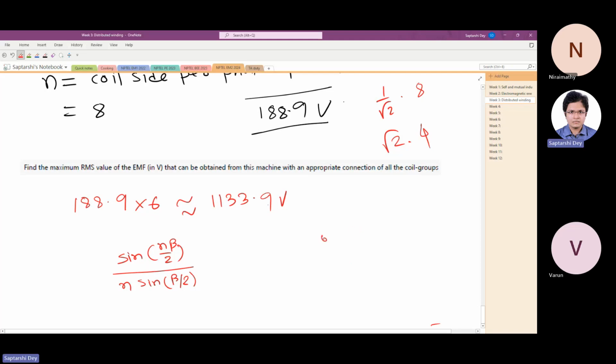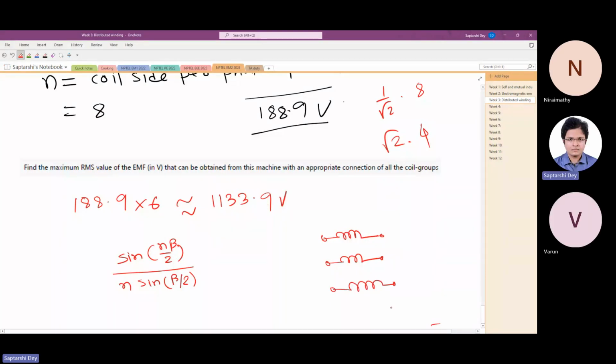It depends. It means if you have 3 coils, how they are connected. So 3 coils are there. Most of the case, what you will get is simply these 3 terminals outside. If it is star connected inside, and they give you the star point also, you can find out the phase to neutral. You have to have the star point outside. If not, one very crude method is there. That is, you put very high values of resistance so that not much current is flowing, and you connect them like this, find out the voltage, and anyway we have the formula.